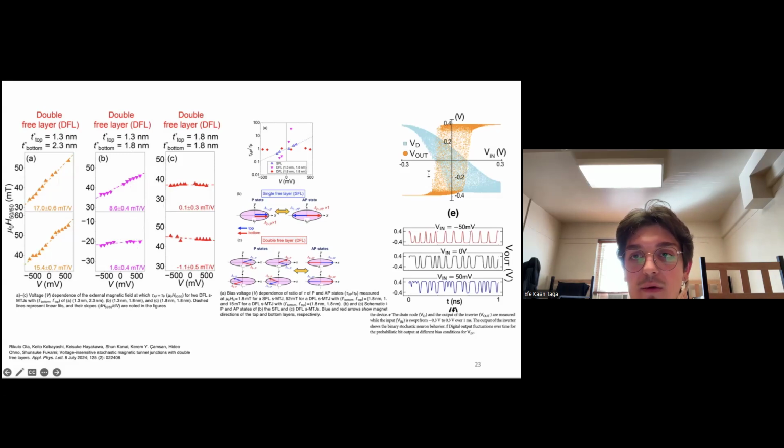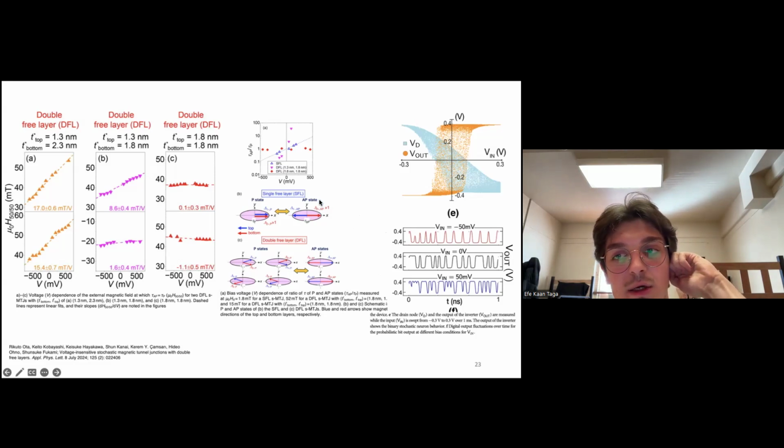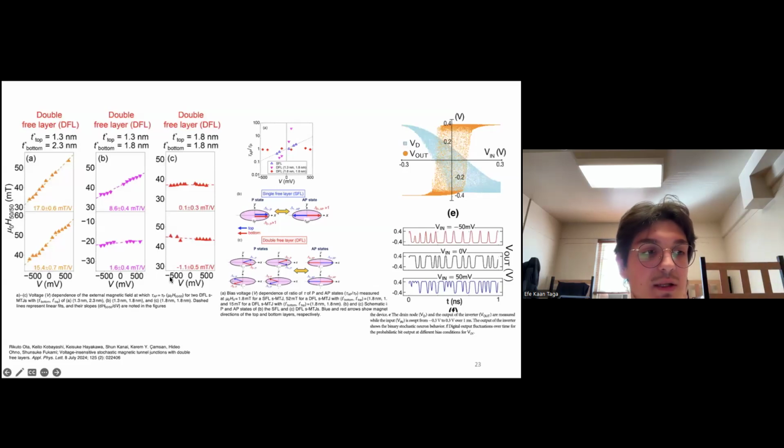Figures 6a and 6b show the full input output characteristic of the probabilistic bit obtained from our full model. There is the characteristic of the bits. These simulations demonstrate the tunability of randomness at different bias voltages. An important point is that the tunability doesn't arise from spin transfer torque effects modulating the free layer magnetizations, but rather from changing the transistor conductance by an analog input. So we change the transistor conductance and the randomness changes. It's not changing with spin transfer torque effects because we constructed it as a double free layer, and it's voltage independent.